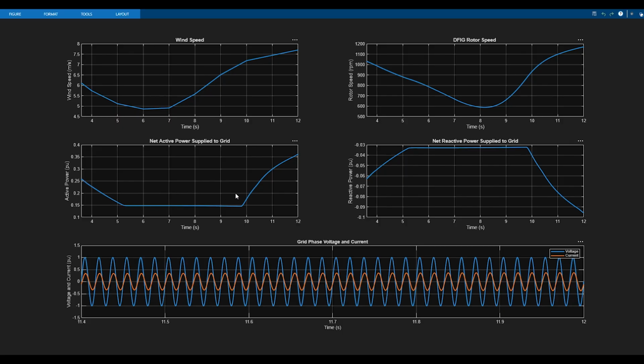The top right graph shows the rotor speed increasing and decreasing based on the wind speed input for that index of time. This is the MPPT algorithm at work, ensuring that the peak power production is outputted to the grid while maintaining a 60 Hz frequency.